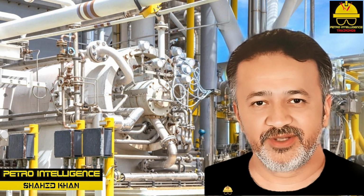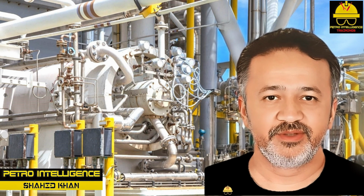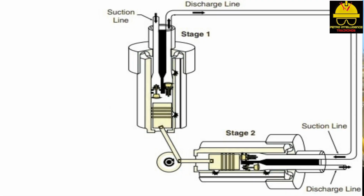Single-acting multi-stage compressors. A multi-stage piston compressor has 2 or more cylinders. The first cylinder usually is referred to as the first stage. 2-stage multistage compressors as shown in picture discharge from the first cylinder into the suction line of the smaller second cylinder. In a multistage compressor, flow rates usually are low and overall pressure is high.